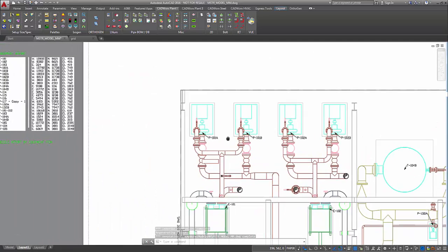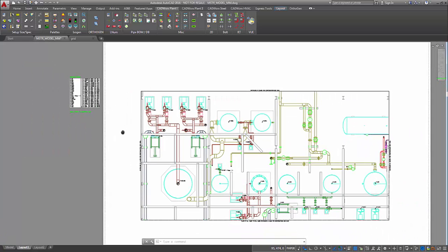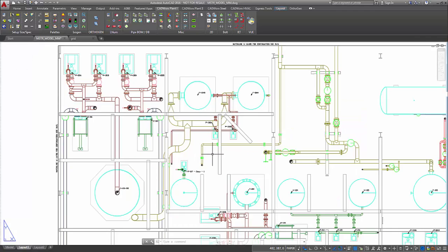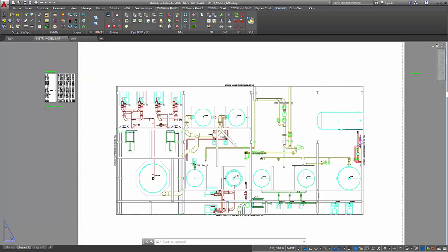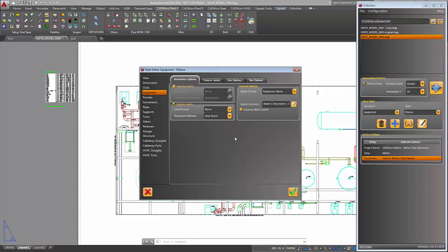But also we had a report block placed in here, E-bomb, a block that marks the insert point for this report. You can see we've got a report of all the equipment on this view. So that's basic for all tagging operations. You can search out a clear space, or you can place it with a fixed offset, go over half an inch and up half an inch and so forth.